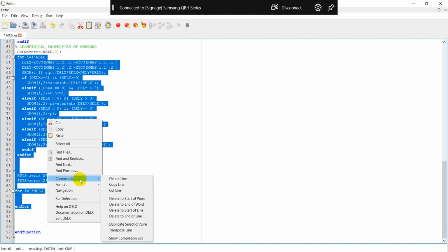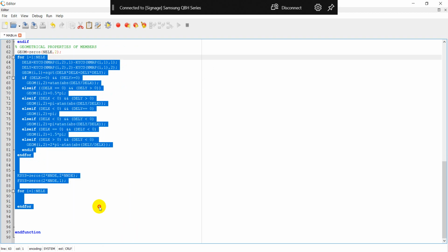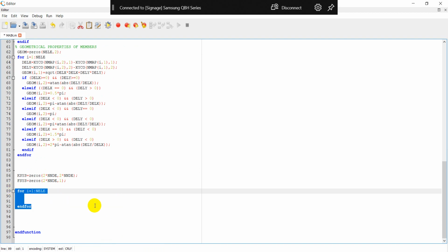Let me check. I just understood something. So this part here, when we conduct the direct stiffness structural analysis, we compute individual stiffness, and then we combine all individual stiffness and reaction force vectors all together, right?